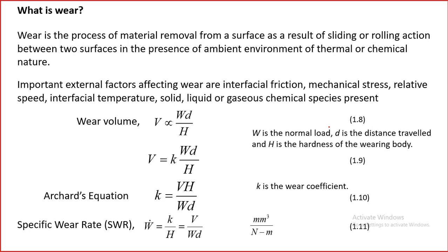We were talking about the wear process, and we discussed that wear is the process of material removal from a surface as a result of sliding or rolling action. So first of all, we have to understand that it is a material removal process. If there is only plastic deformation, we do not call it wear. Wear means the material has to be removed.